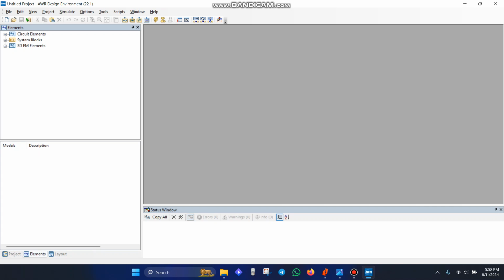Alright, hello everyone. So this is a guide video for the AWR and Axiem RF simulation software. In this video, I will be designing a simple RF circuit in order to show the steps involved in designing the circuit and then obtaining its Gerber file in order to have a physical PCB of that circuit. The simple RF circuit that I will design with this tool would be a filter, and then we would perform some geometrical tuning in order to optimize our design requirements.